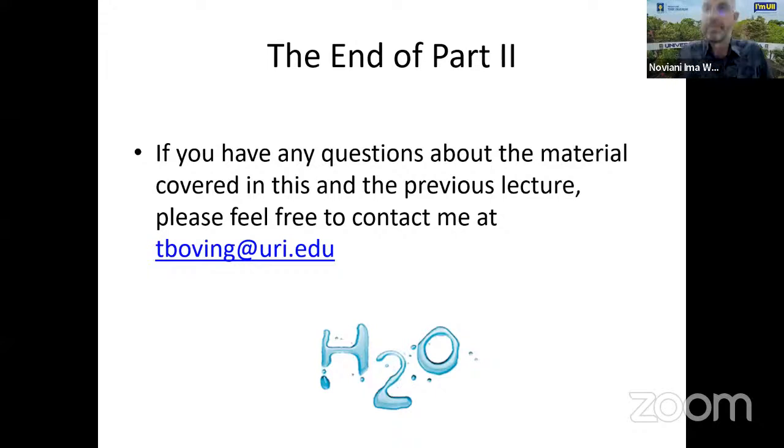Thank you for your question. The answer to your second question is that the type curve will remain the same always, and that's the beauty of the method. Once you have plotted the data, W(u) versus 1/u, you only do this once in your life. Or you can use a copy of my slide, if you like.